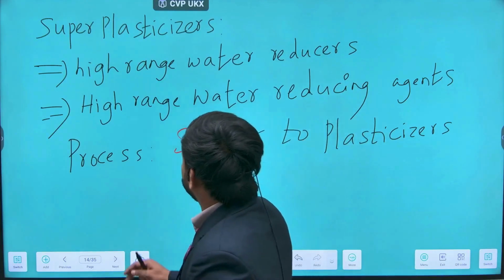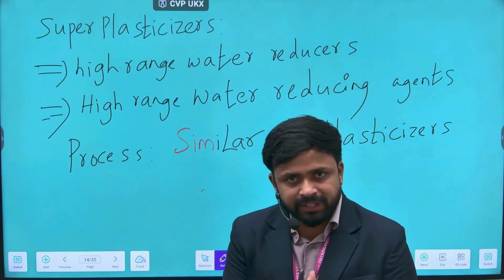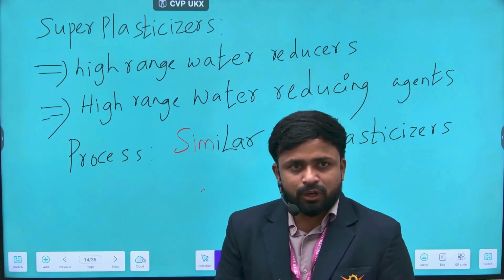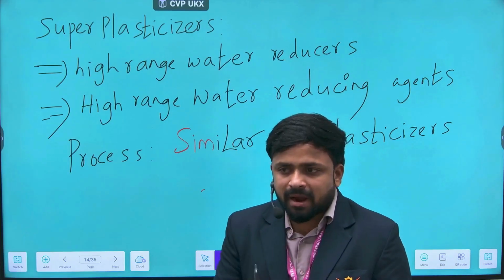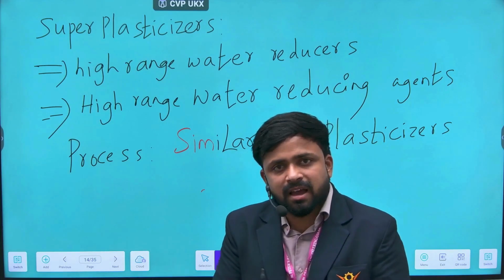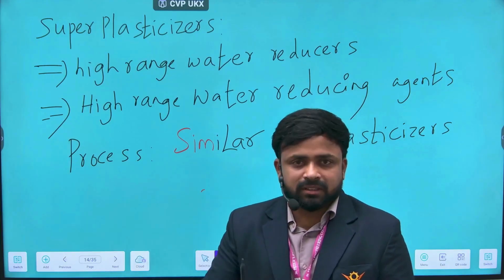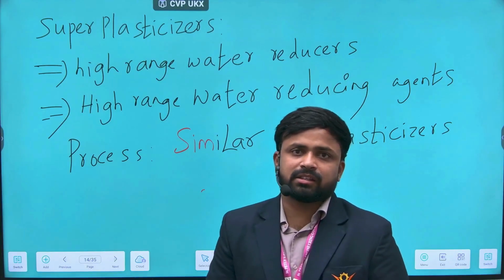These are also doing the same process. What they are doing is breaking the friction between the particles, and due to breaking down of the friction, the particles can slide over each other, thereby the workability requirements are achieved, and thereafter the strength and durability characteristics as per the codal provisions are achieved.